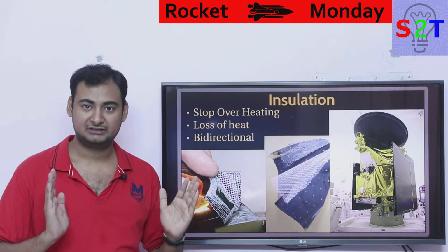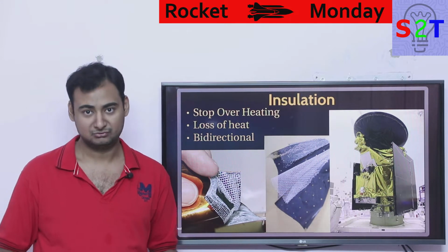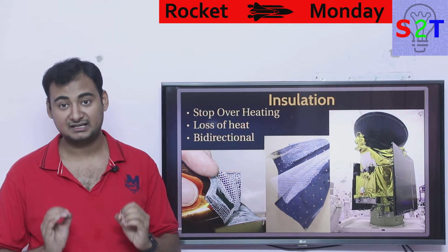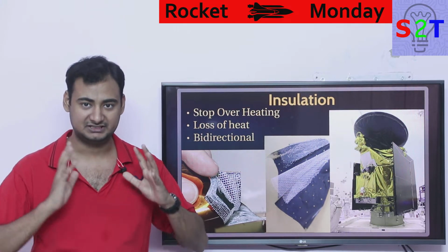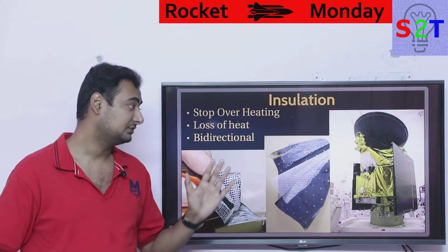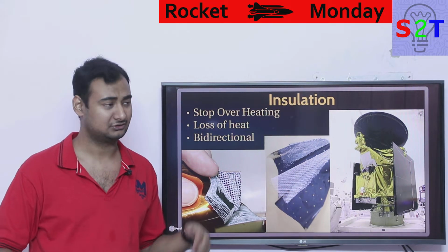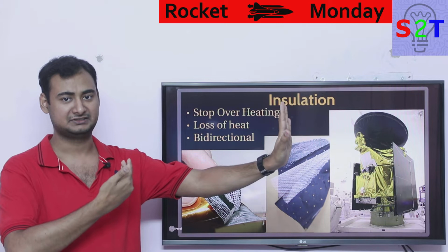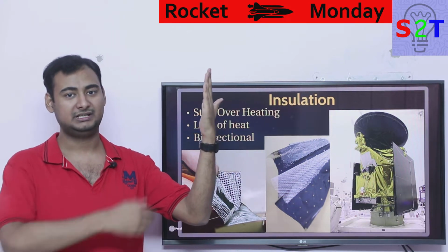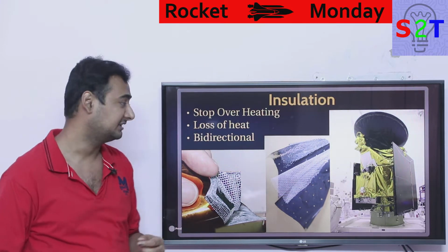If you have a limited mass, let's say you cannot put more than 10 kilos, gold would be better than aluminum. So gold foil is very good at stopping infrared, and our sun, a specific star, is very hot in infrared. It's giving off a lot of infrared. It's not giving a lot of gamma rays or x-rays, but it's ludicrously bright in infrared. So if you can stop infrared, you can flat out take care of most of the solar energy. Okay sun, I take care of your infrared, and there's not that much x-ray or gamma ray that I put on the gold foil and this side is still melting. That won't happen because our sun is not very bright in x-rays or gamma rays.